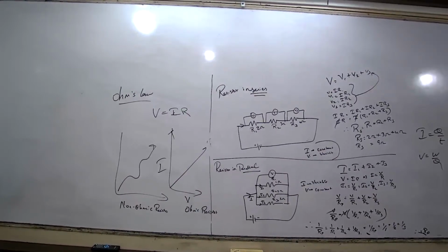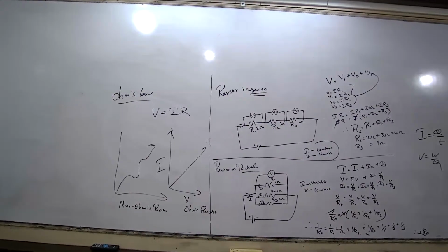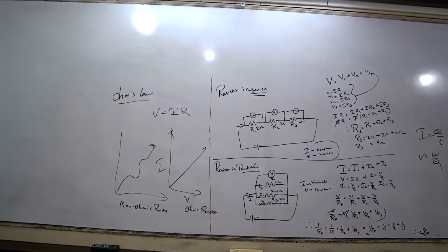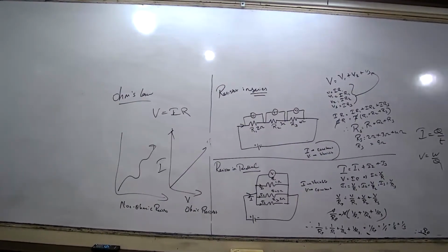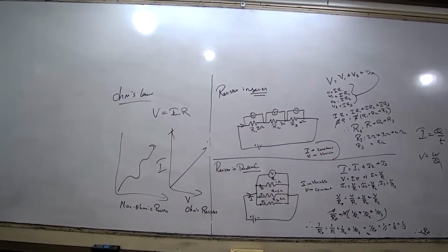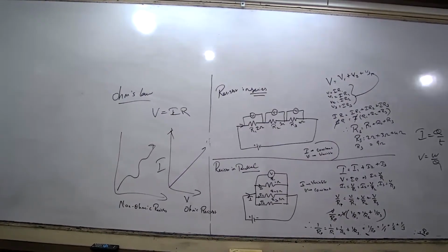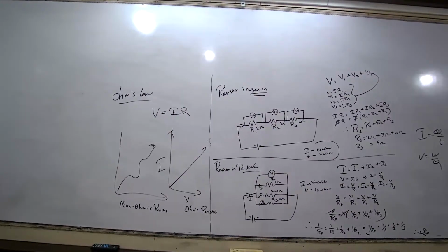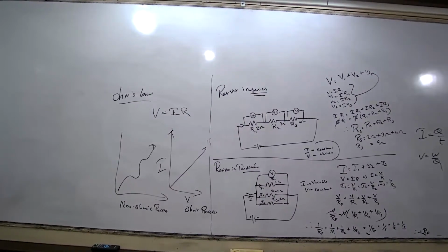In heating circuits, we are going with the nichrome. Why? Due to the heat effect of the current. I told you when more current passes, it creates heat. Nichrome has high resistance, so it restricts the current. Copper is allowing all the electrons, so it has low resistance.